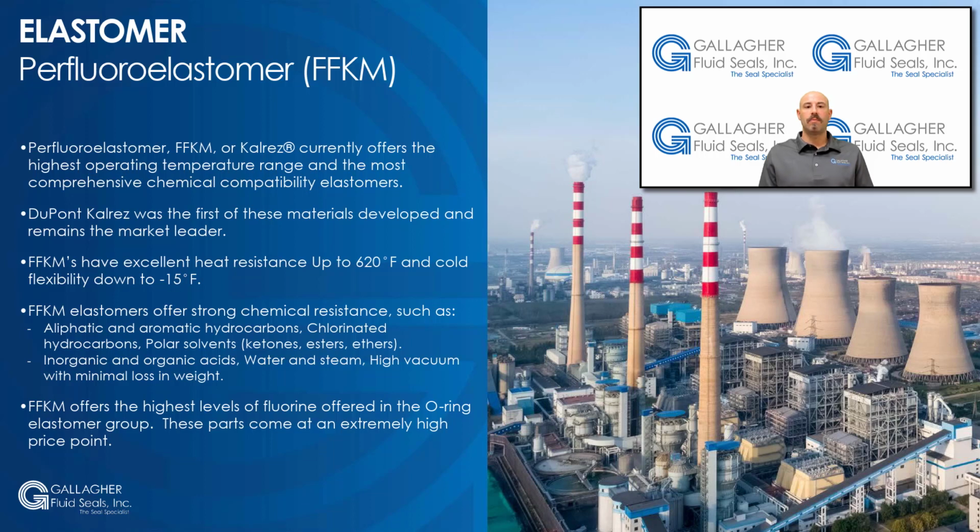FFKMs are not compatible with the following: fluorinated refrigerants such as R11, 12, 13, 113, and 114, and perfluorinated lubricants, or PFPEs. Key takeaways here are: FFKMs offer even higher temperature performance and chemical resistivity than FKMs.